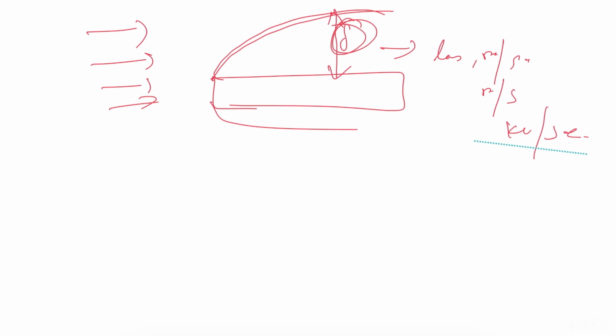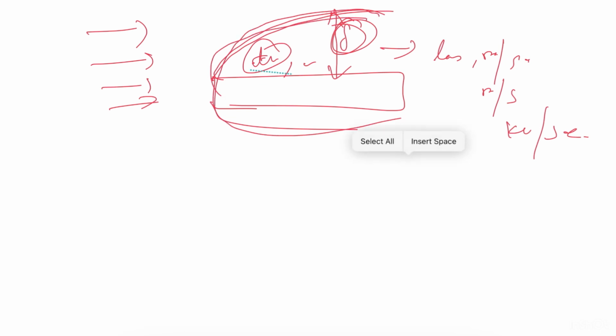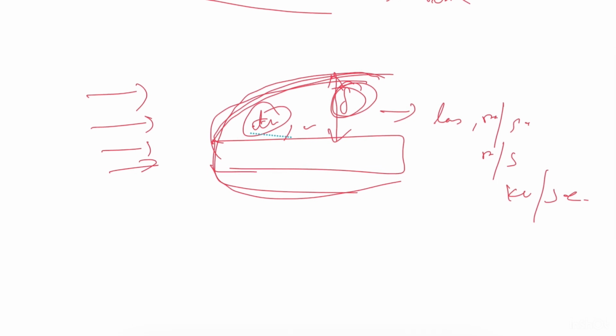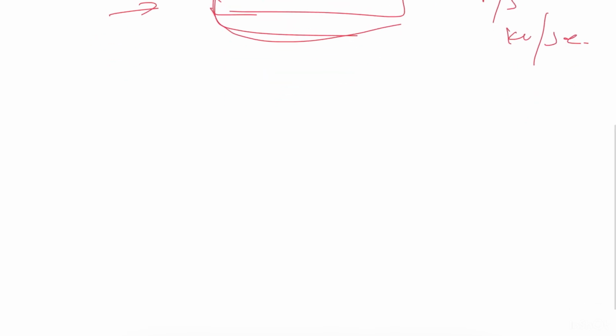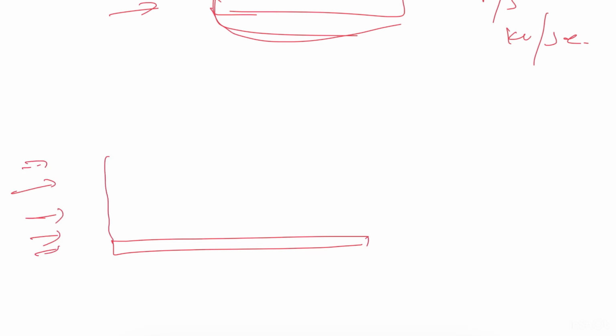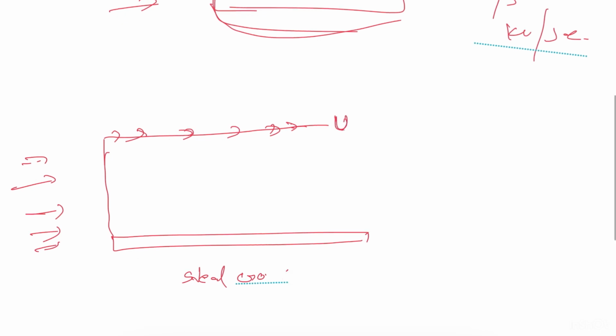To compensate for the loss of mass, momentum, and kinetic energy in this boundary layer, the same amount of mass of fluid flows with the displacement thickness. This is the plate, this is the flow of fluid. This is the ideal case of fluid flow, where there is no formation of boundary layer. This is the solid plate.